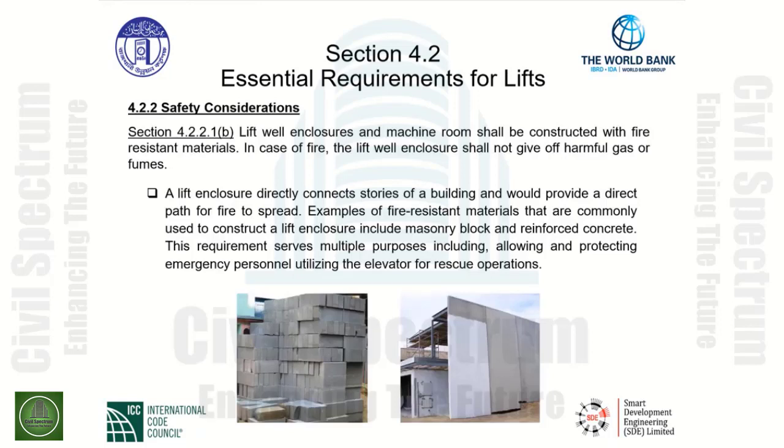Safety considerations is indicated in section 4.2.2. As we move through this particular section to item B of section 4.2.2.1, there is a requirement that lift well enclosures and machine rooms shall be constructed with fire-resistant materials. In case of fire, the lift well enclosure shall not give off harmful gas or fumes.